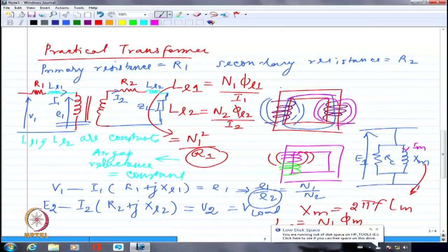Im is almost the same as I0. I am going to come to that. Please remember that I have also shown one more parallel path. The parallel path is definitely not talking about only inductive current. It is talking about a resistive current. So when I add the resistive current corresponding to core losses with that of the inductive current, which is the magnetizing current, I get the total I0.